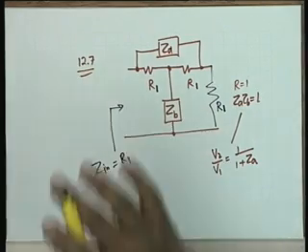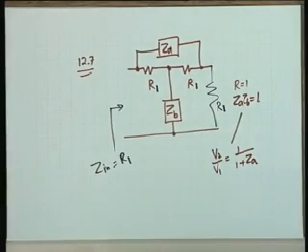Why do we terminate by R? One at a time. Suppose you were to terminate by R2. Then it would not be a constant resistance network. The input impedance would not be R2. So that means that whenever the resistance is a part of the network itself, you have to terminate only by that. In this particular network, yes. There may be others in which the resistance is not part of the network. For instance, in 12.4 also, we had R used within the network itself. Correct, R is used in the network itself.